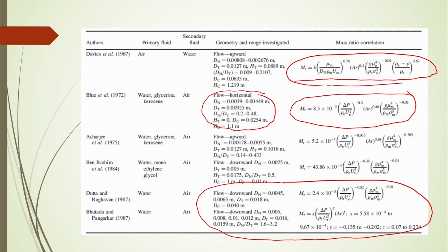In that case you will see that kerosene entrainment will be very difficult, because the viscosity of that CMC solution will be higher. The entrainment of that kerosene will be more difficult, as more resistance will come from that liquid. So their contact, between the kerosene and the carboxymethyl cellulose highly viscous liquid, will be less, mass transfer will be very less, and even more interfacial area will not be produced whenever you are using a highly viscous liquid.